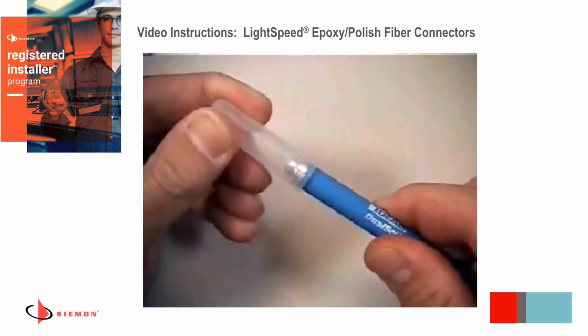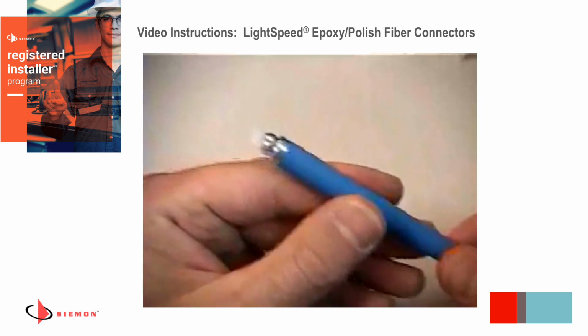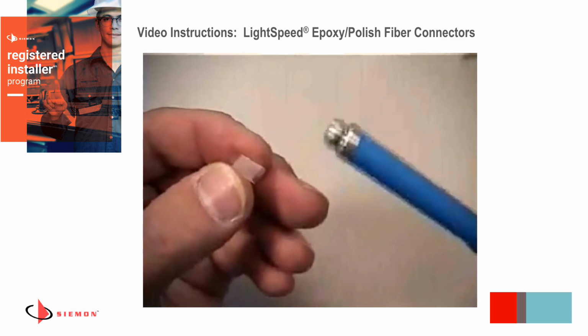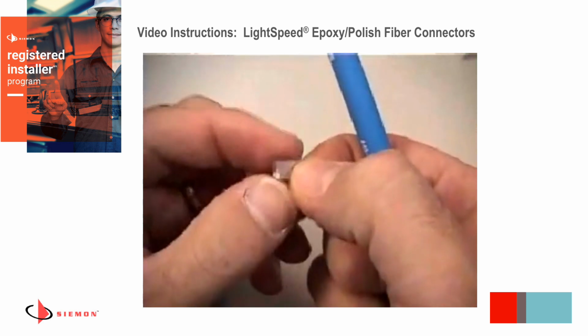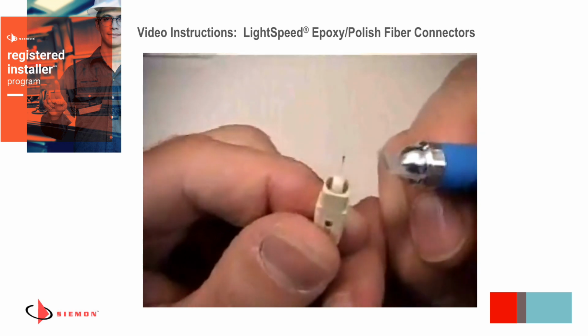After the adhesive has cured, you are now ready to score the excess fiber using the scribe tool. First, inspect the blade to ensure it is clean and in good condition. The sapphire blade is double-edged and may be reversed if one side has been damaged. Hold the blade of the scribe tool flat against the ferrule tip with the beveled edge facing up.